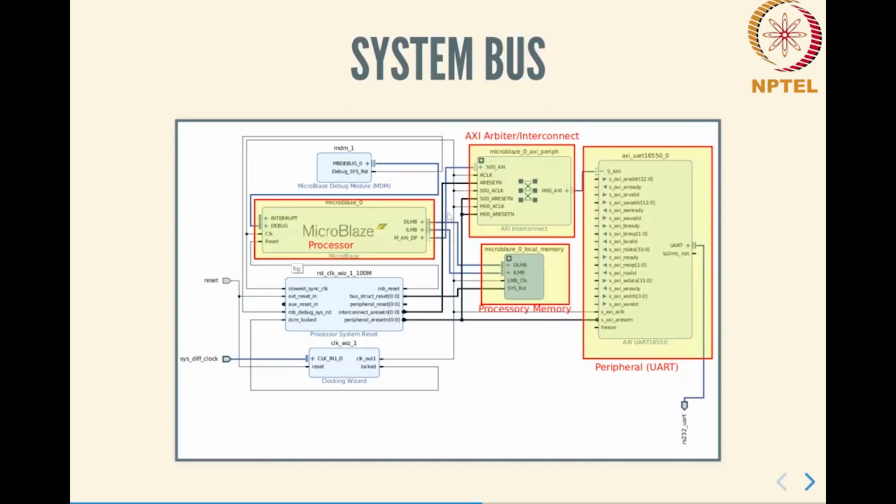The wire leading from that AXI data port essentially goes to something called the AXI arbiter or the AXI interconnect, and it goes to the S00_AXI interface of that, which means basically that that's a slave interface on that arbiter. The idea of masters and slaves will once again be explained a bit more in detail when we look at it with examples. But the important part over here is that the AXI arbiter is the one that takes care of connecting between the MicroBlaze processor and the peripherals.